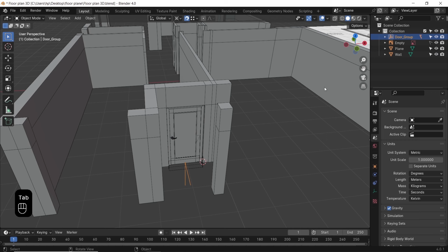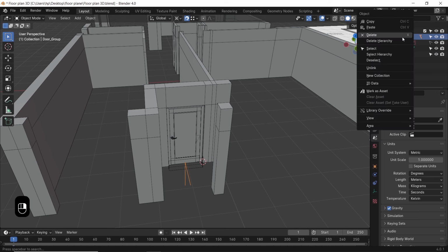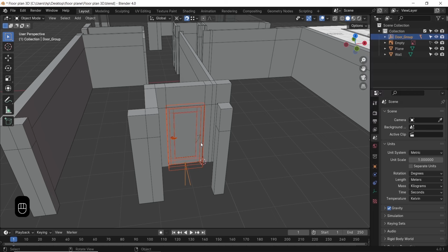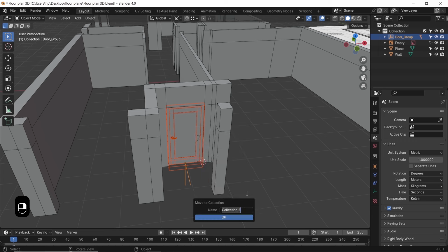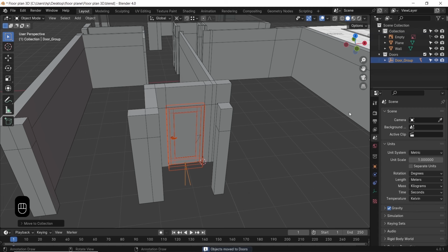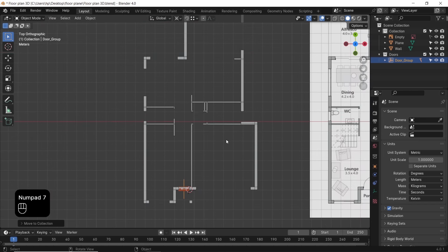To copy the door around, we can first put it in a new collection to keep things organized, then select the door from the layers or from the viewport directly, and hit Shift-D to copy it. Keep in mind, you need to select all parts in the door with the empty, so you don't generate any unwanted problems. We have another 5 doors to fill, might need to fix the width and rotation in some of them. You can check with the drawing image for the door opening direction.